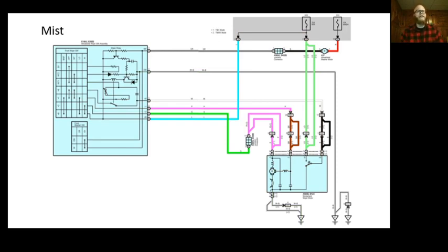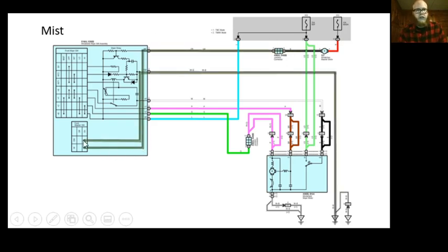All right, on to something easier. When I want my washer to wash, I've got my washer motor up here, so power comes in, and then this is the only load, so it should drop it. And you can see how it comes down into my switch, and then here's my ground circuit out of the switch right here. So it should be power, and then the rest of it's just ground because I dropped it all across that motor.